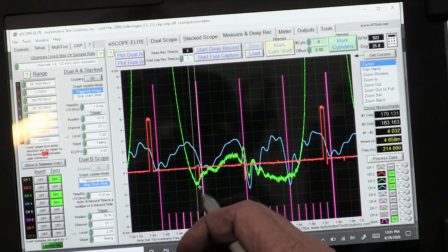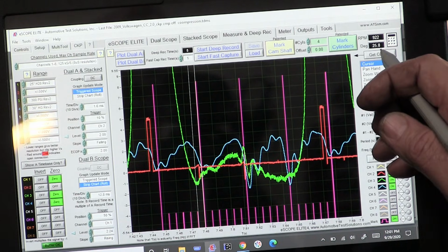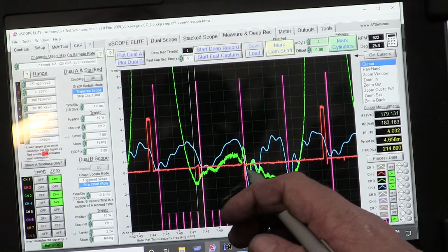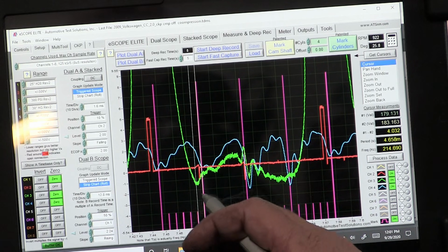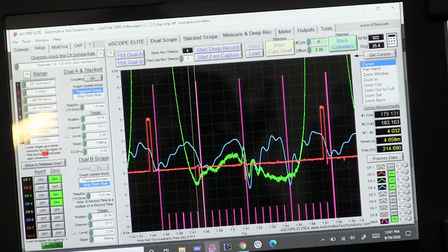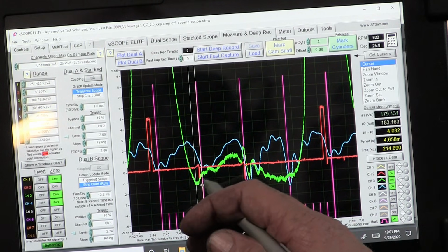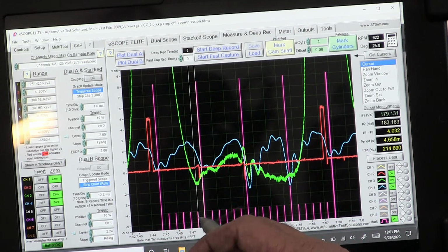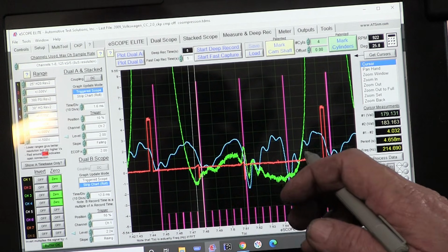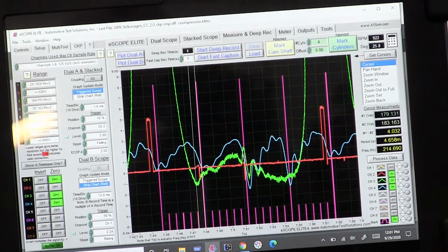Now we can see that in this pocket, we're opening about 25 degrees. We really should be at 30, but since we really don't have a lot of vacuum, this might be a little early when it's actually a little further over. The exhaust is closer to being timed correctly because that's within just several degrees. The intake is 50-55 degrees off.